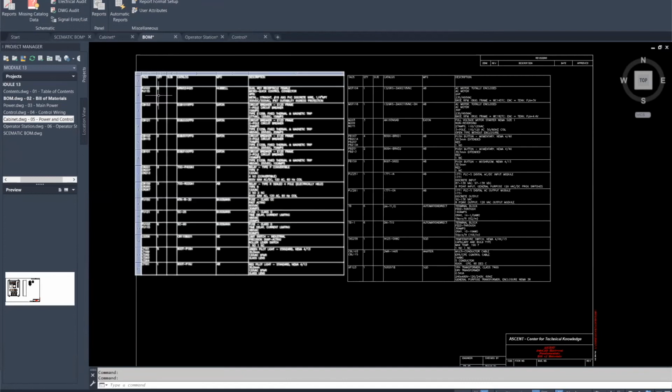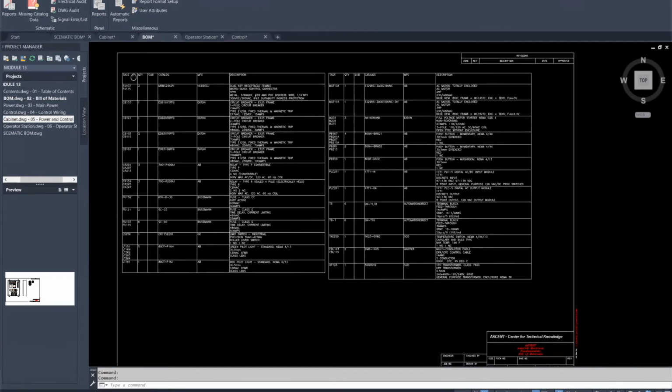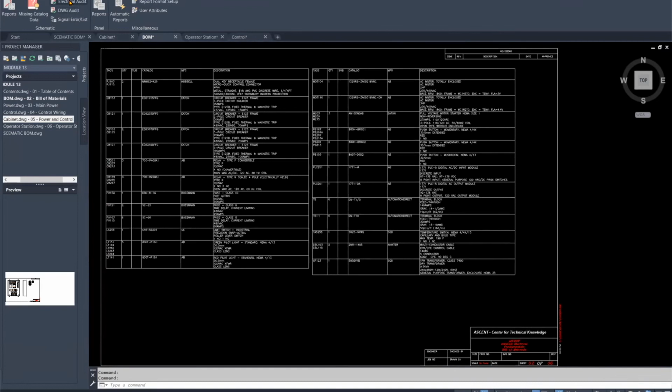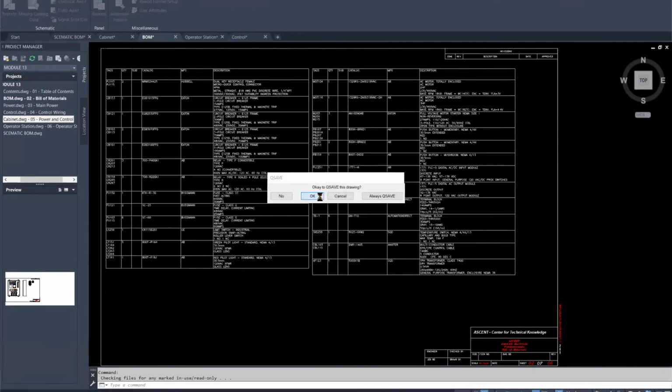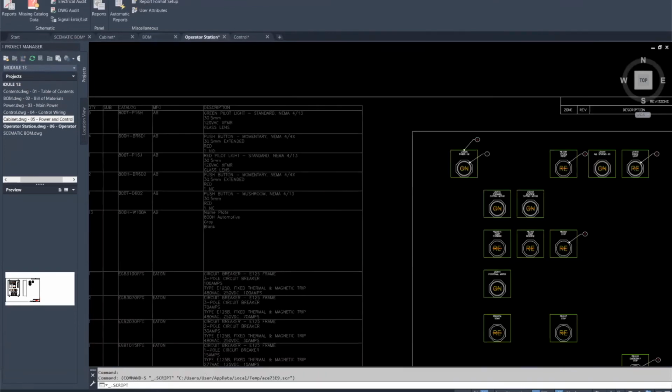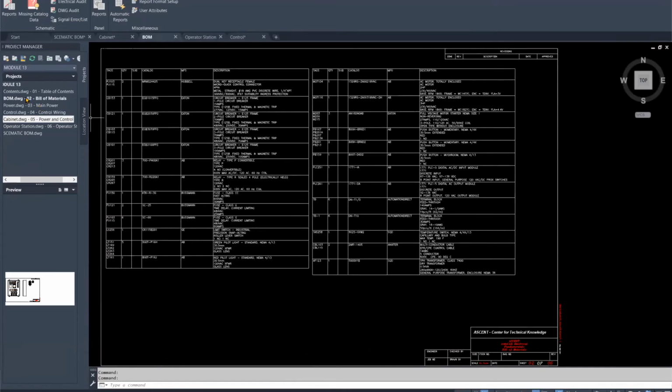And then within AutoCAD there is also a feature for error checking. If I've got my project all done, and I've made changes that aren't done yet, I'm going to make those changes now. It's going to update my project with the changes I've made so far. And now all my manufacturer's CAD numbers and catalogs are the same across schematics, panels, and bill of materials.